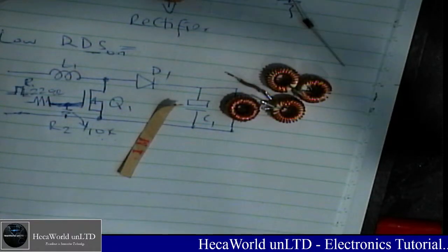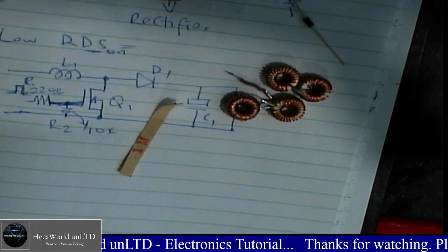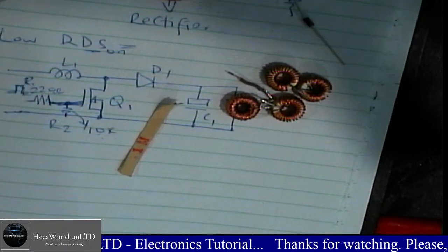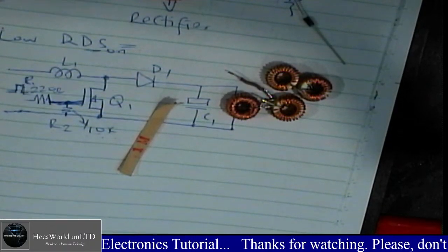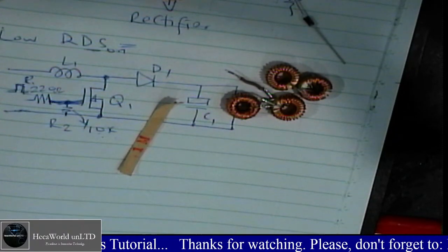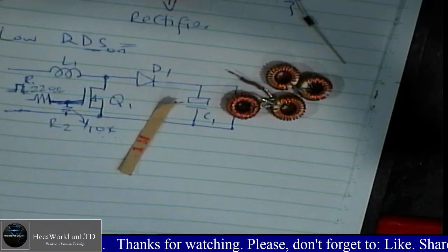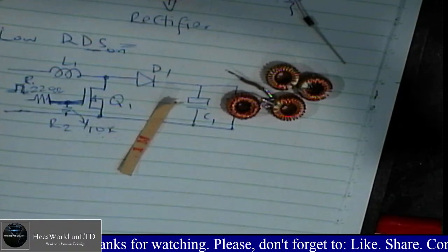Alright, I haven't seen the inductance meter, but I have the oscilloscope, tiny one. We're going to use that at some point. But we need to first of all measure the inductance of the inductor we want to use so we can calibrate properly. But without the inductance meter, I think we can still go ahead.